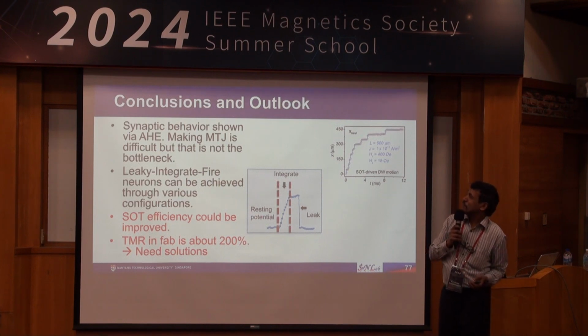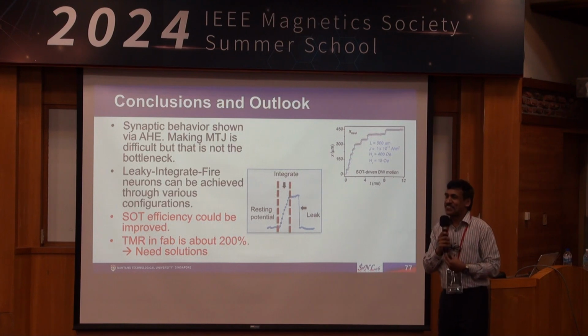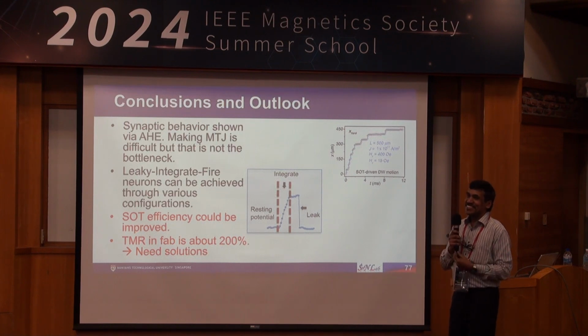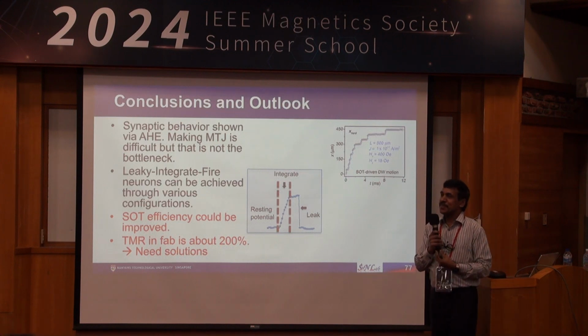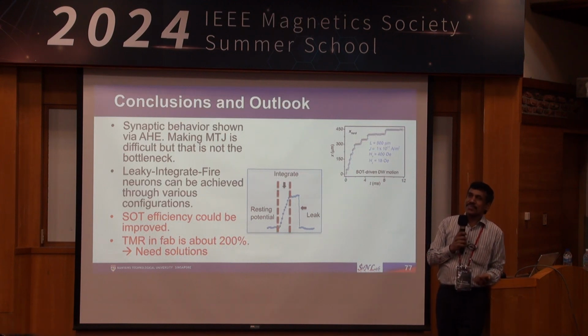Okay, I chose magnetic material because I'm working on magnetic materials. That's one thing. That is a frank answer. But if you want to say why the domain wall devices are better, we can say, considering the endurance. If you take phase change materials, when you change the resistance, basically you are moving the atoms. So usually the endurance is lower.